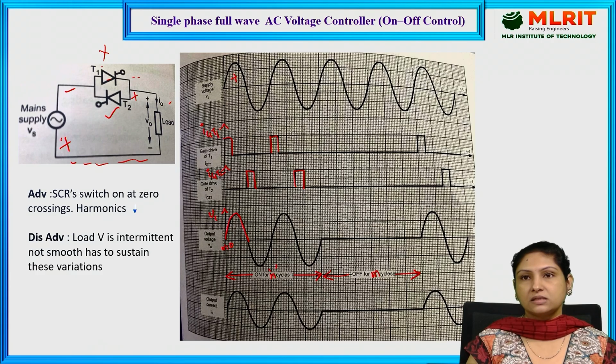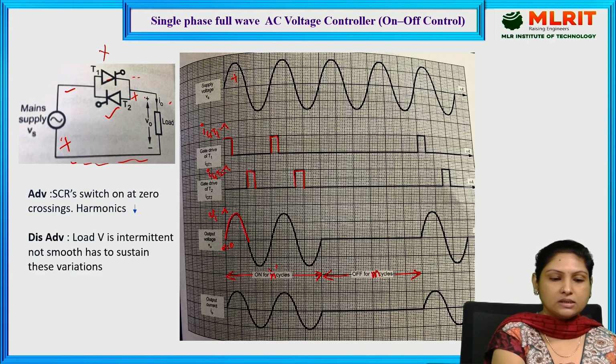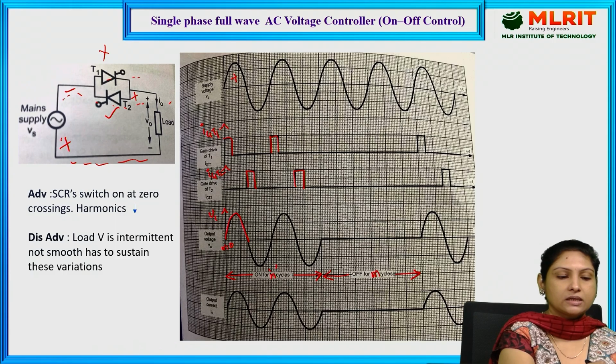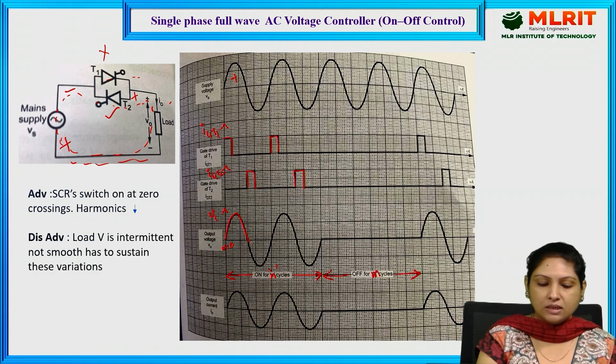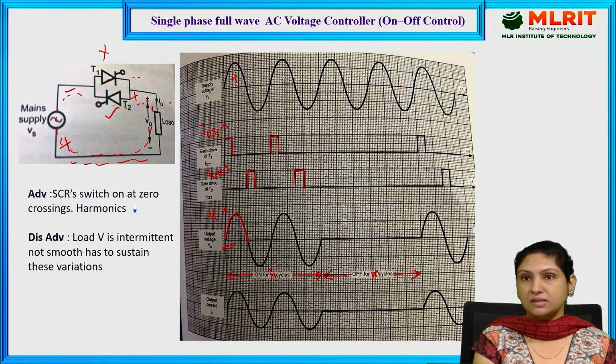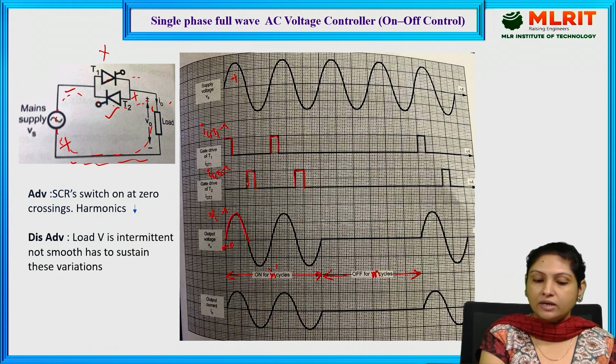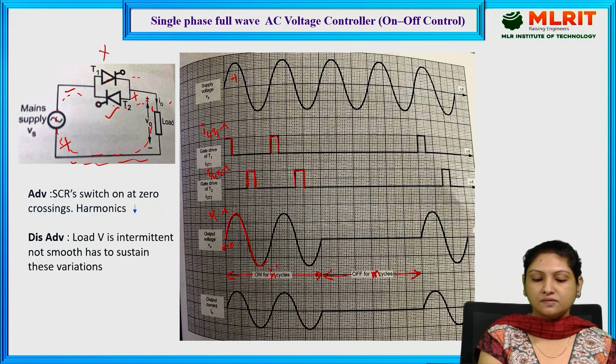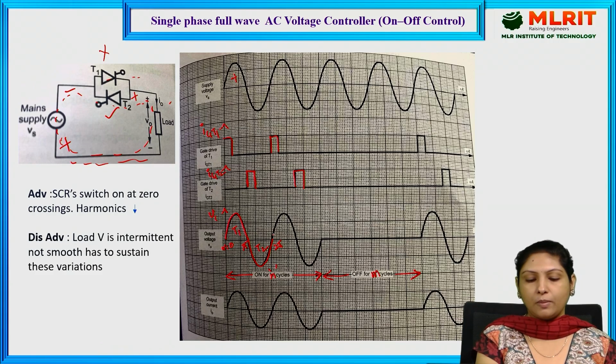It is acting as an off switch during the negative half cycle. So that is how T2 starts conducting current through the load in this direction. And if you see, at the instant alpha is equal to 0, we have provided the triggering pulse for thyristor 2. That is how thyristor 2 is conducting during the negative half cycle till 2 pi. See, thyristor 1 has conducted till pi, and thyristor 2 is conducting from pi to 2 pi.